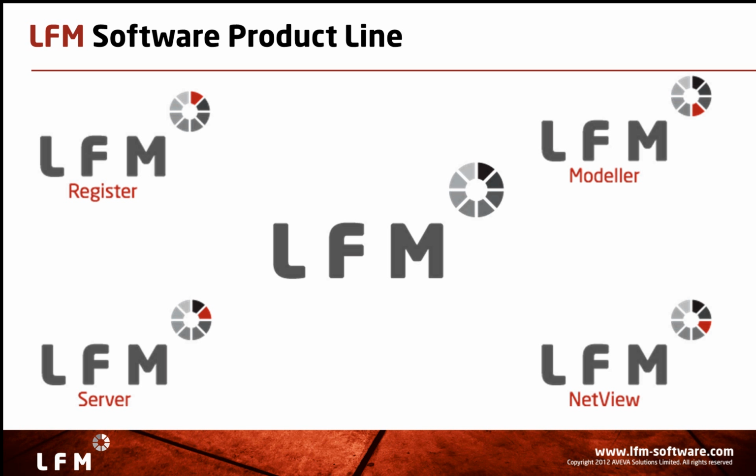Some of you are quite familiar with these logos. So these are the products that actually form the LFM software portfolio. The LFM Register side of things will ensure that you can bring individual 3D laser scans together and then create a uniform project coordinate system. LFM Server will make sure that you can connect with various CAD systems and also allows you to handle large databases. LFM Modeler will handle the modeling side of things, which is all about modeling from point cloud data in order to create a 3D model easily and rapidly.